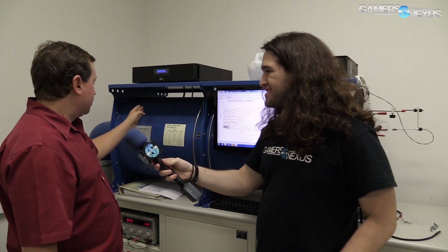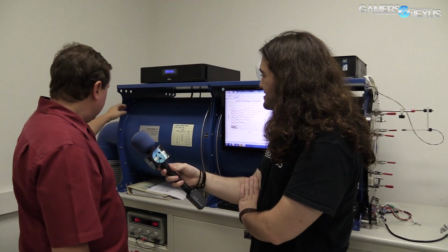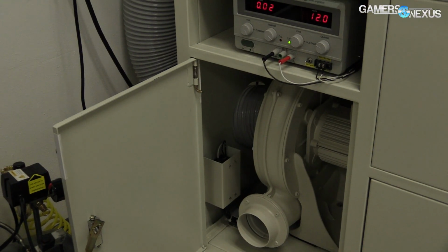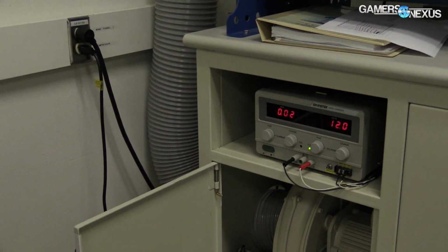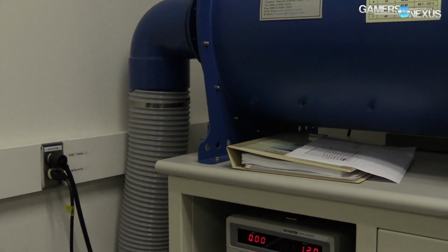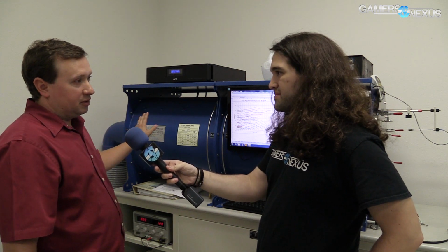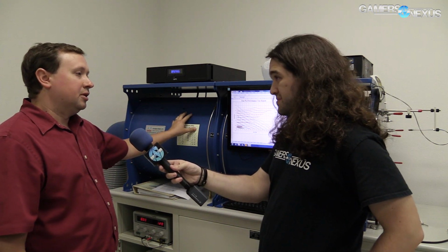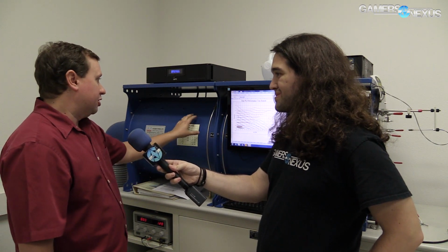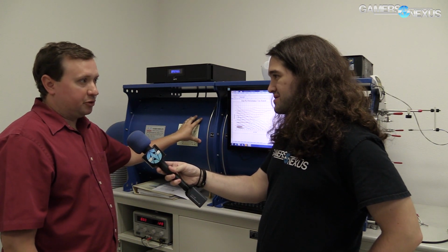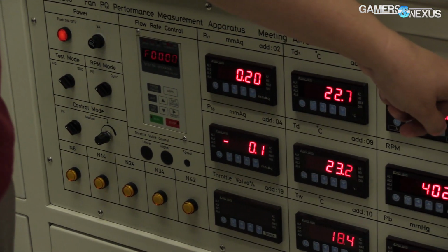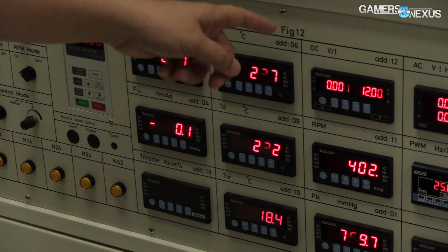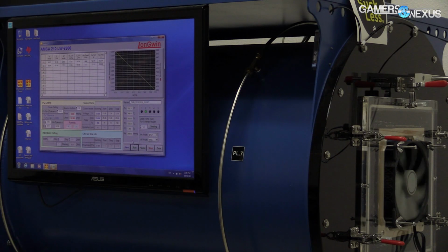This chamber has a couple more screens in it to equalize the flow, and then that tube goes out to a big fan right there. That's the counterblower. This is necessary because the wind tunnel itself has significant airflow resistance, and so it actually pulls a vacuum in this chamber in order to get the flow that it needs to achieve in the first chamber. This chamber often operates below atmospheric pressure. That's normal. So in order to get this point here to equal atmospheric pressure, this chamber here has to be significantly below atmospheric pressure.